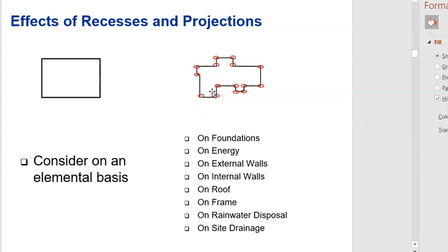And all of those additional elements, additional design shapes and features, if you like, cost money. They have a dramatic effect on cost. The most efficient structure to design and build is a simple square or rectangle in most cases. Because of spans of timber, the rectangle is going to be the most efficient structure. And then if you think about energy costs, you're also going to have a huge saving by having a compact rectangular structure.